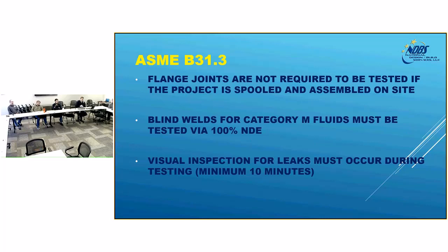So as you're developing your sequencing of construction for big systems like this, and if there's a borescopic inspection required, for example, you have to make sure that it's built in such a way that the 25-foot borescopic camera or 50-foot camera can always get to the welds that you're laying. So how it's actually put together in the field becomes somewhat of an issue. You can't work over here and over here and over there and then join it up in the middle. You have to work from one side and work your way back. So it's just something to think about. So you have to be thinking about your NDE requirements before you even start construction.